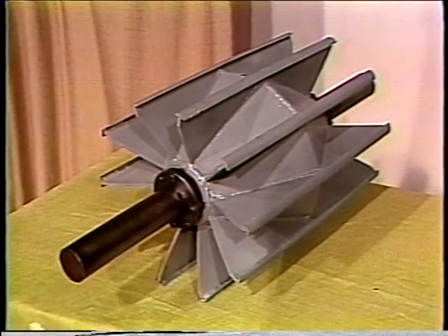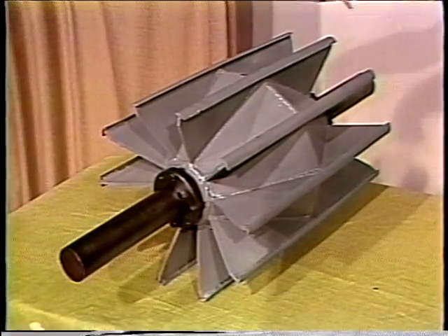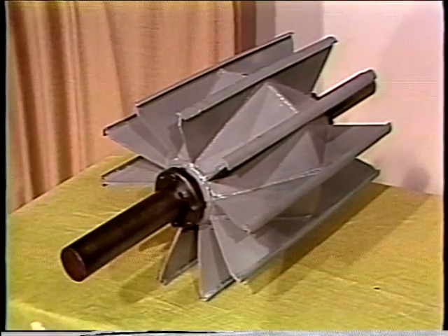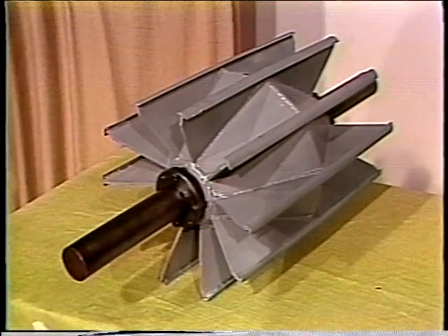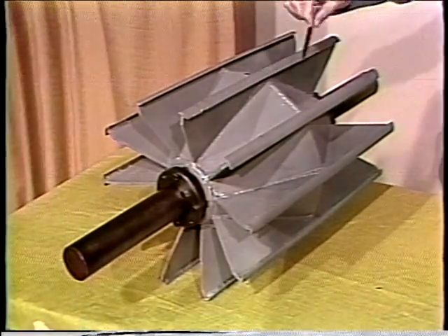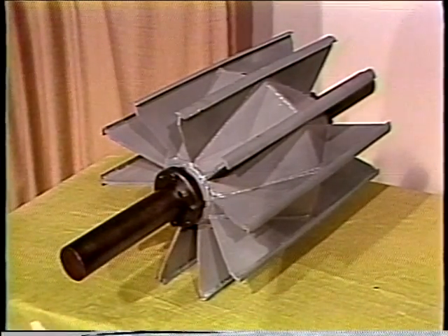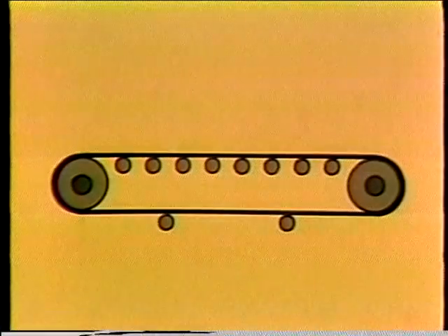Now, tail pulleys are usually similar to the head pulleys. However, there is a pulley used for certain applications where there is a tendency for buildup on the pulley, or where the material may be trapped between the belt and the pulley. It's known as a winged pulley. When any material falls on the pulley, there's an opening which allows the material to move out the end. These are most frequently used as tail pulleys on elevators and inclined conveyors.